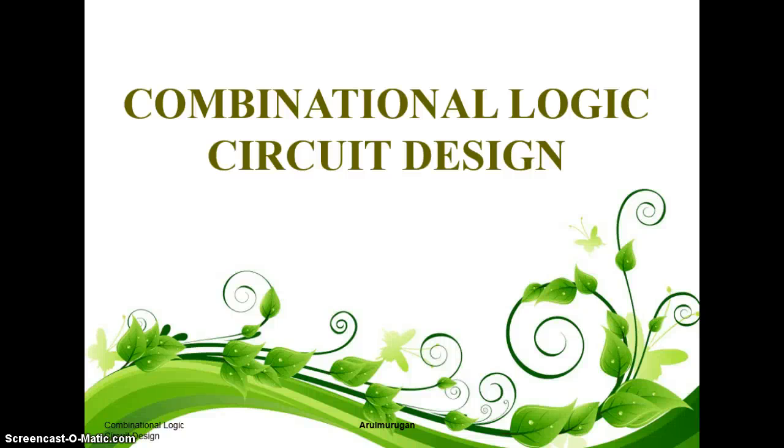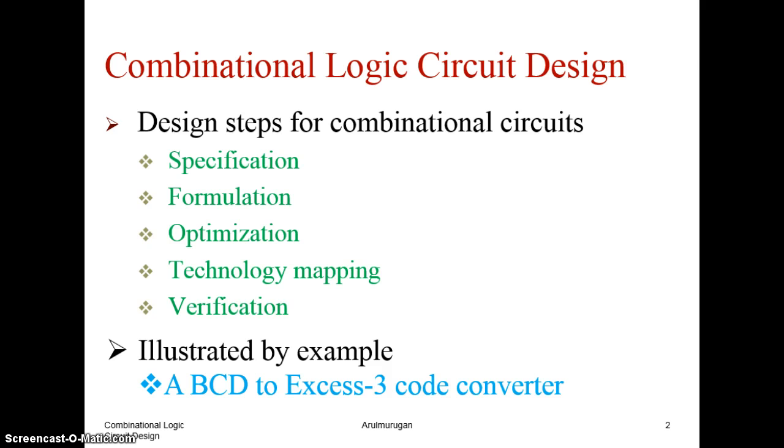The presentation is focused on the design of combinational logic circuits. The design steps for combinational logic circuits involve five steps: specification, formulation, optimization, technology mapping, and verification. These design steps can be explained with the help of a BCD to XS3 code converter.